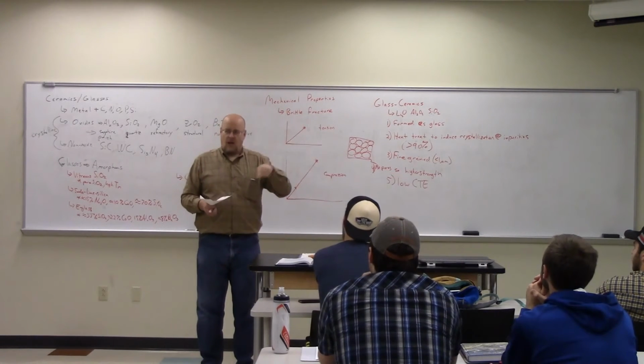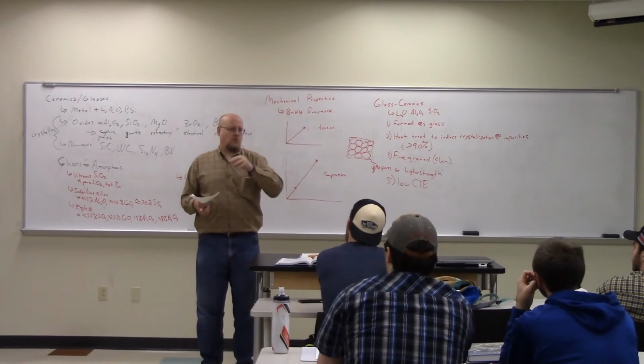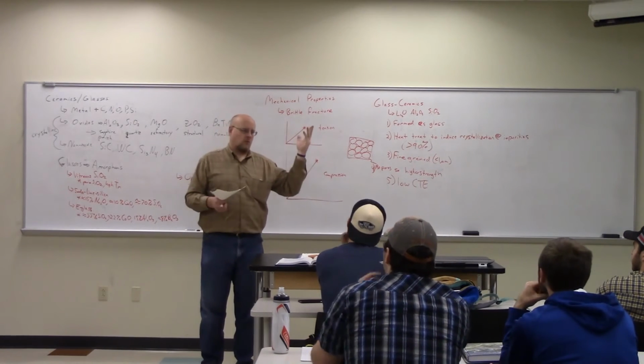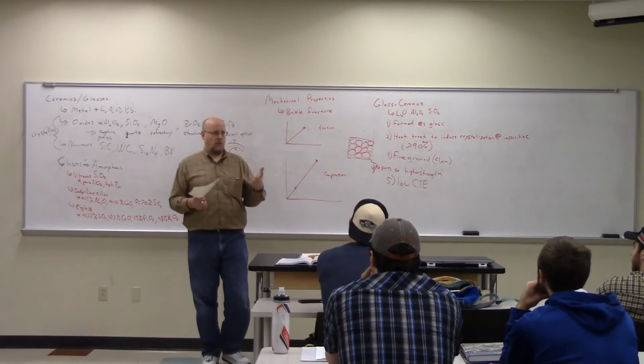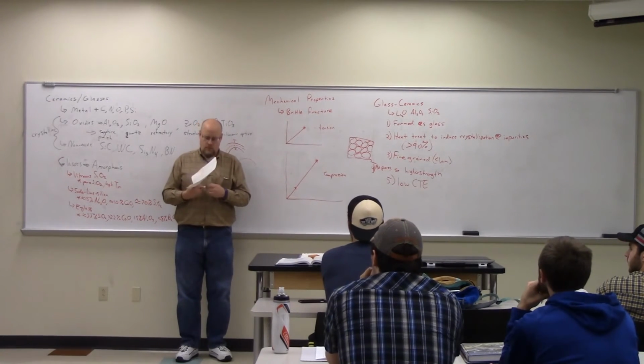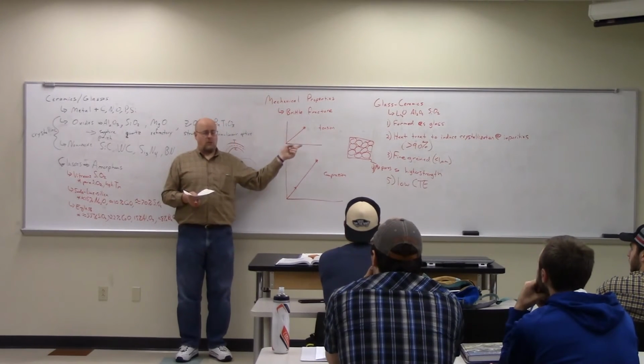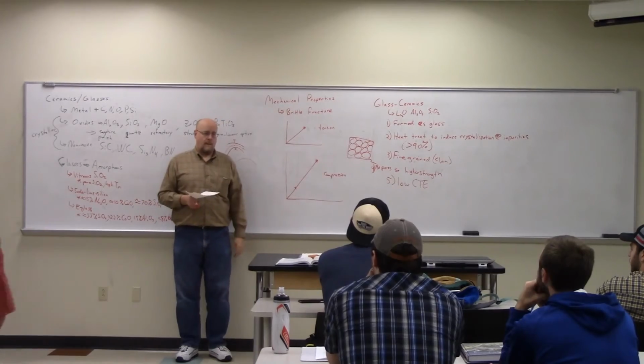If I drill it, I've got to have a diamond scratching through it, and so if I drill a hole, I'm going to leave defects, cracks in the surface that I don't want there, and it's going to weaken the material. You could heat treat it after you drill it, right? To reflow it, yeah, but only if it's glass. Once it's ceramic, it's not going to reflow properly.